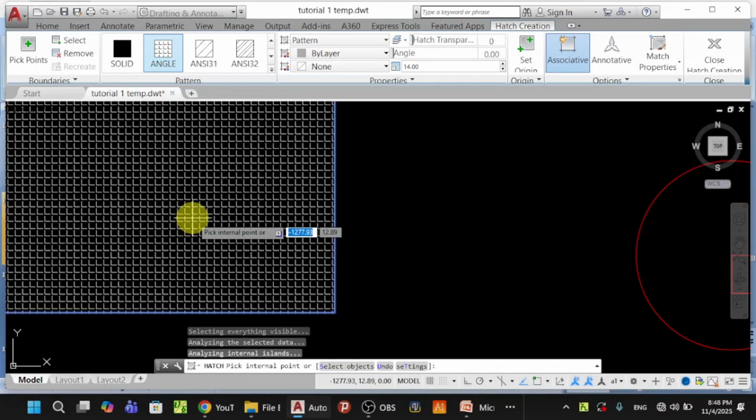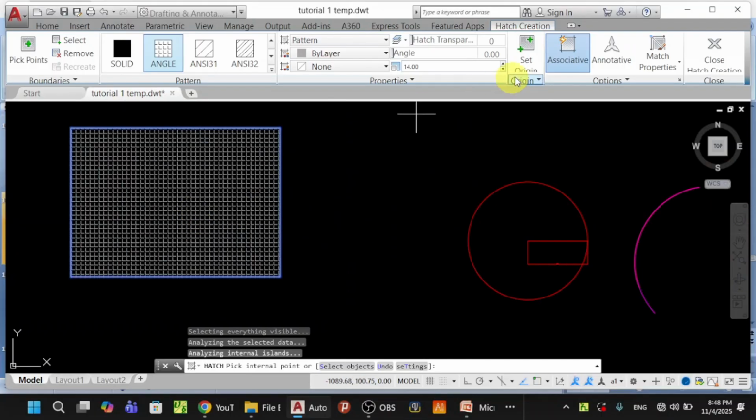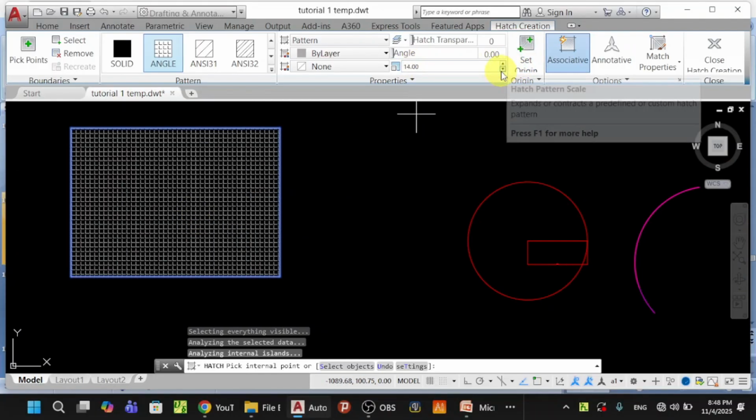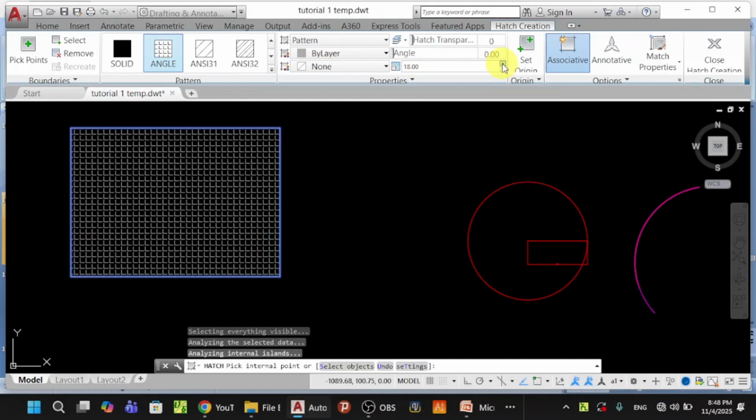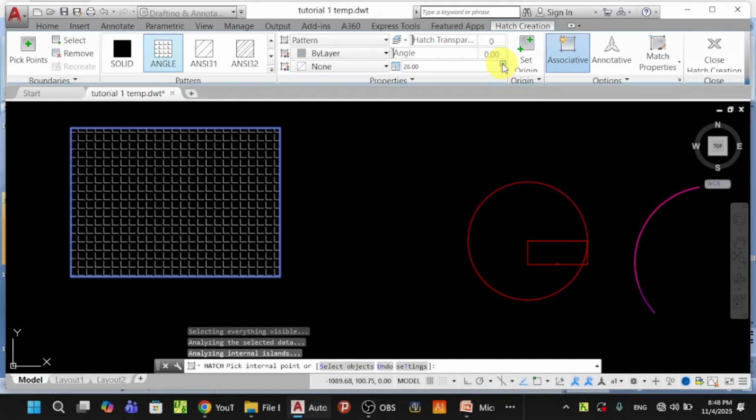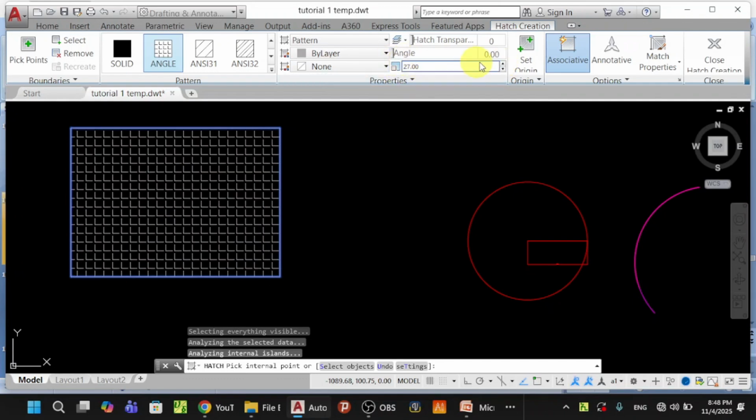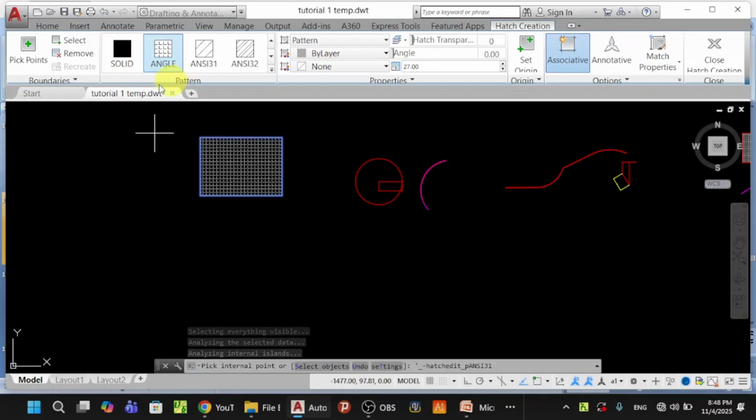Then this is hatch. You can change the scale right here. It says 40, but you can increase or decrease. 50, you see, more visible. You can increase a little bit. Here is the scale area. Angle, you can change the angle of the hatch. This is how you do a hatch. It's to show corridors and something, a cut area, the cutting material, a cutting tool passing through something, and if you want to show it with a hatch, that time use a hatch.